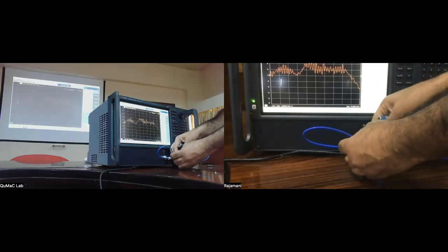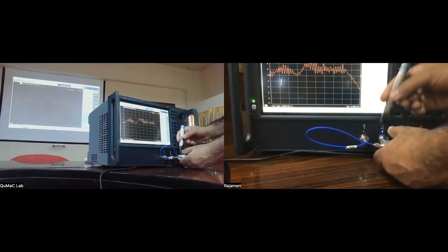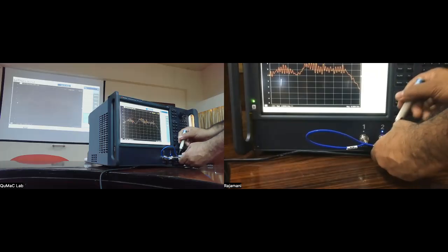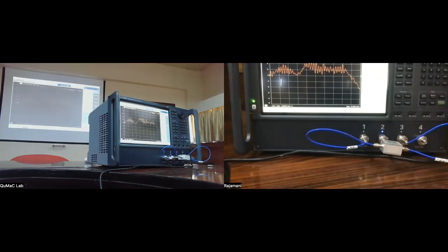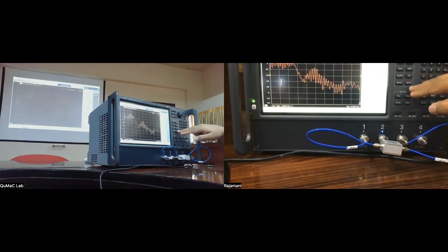So this is a different type of splitter, which works all the way down to DC frequencies. That is actually not possible in the Wilkinson divider geometry because of the principle it uses to do the splitting. This is actually more like a voltage divider. When you want to divide a power, what do you do in DC circuits? You do a voltage divider. That's why this one actually works all the way to DC. So let's not worry about the phase for this one.